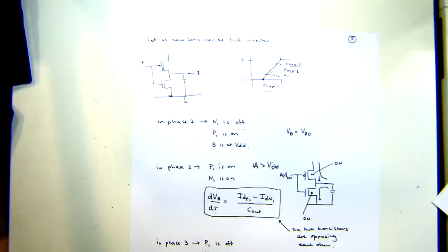ARM does now. There used to be a company called Artisan that used to do them also. When you're writing the Verilog code, and after you synthesize it, you say, well, I want an AND gate or an OR gate or whatever. It grabs it and instantiates it from that standard library.